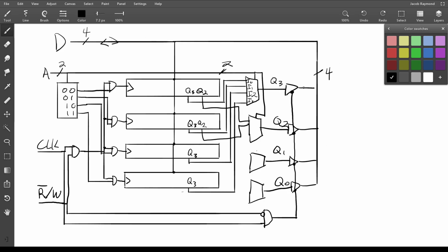And then when we're reading, the data would be coming out here, and you might think, oh, well, it's coming back here. But keep in mind that this value here has to be a 0 for this to output anything. And if this is a 0, then this input here is a 0, right? Because we're reading and not writing. And so we're not actually going to pass a 1 here to do a write. And so all of the inputs here to the registers are going to be 0, which means that we're not going to write anything. So there's no problem in that data getting sent over here, but it allows us to use this wire in 2 directions. And this is a memory component. That's it. There's really not much more to this.